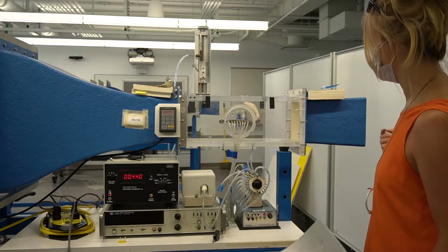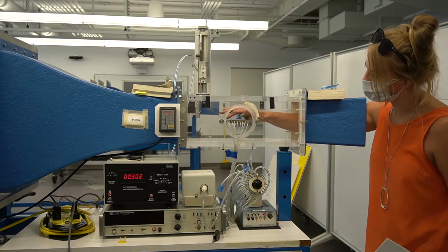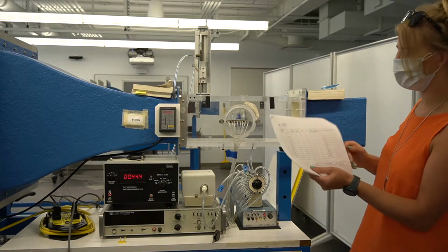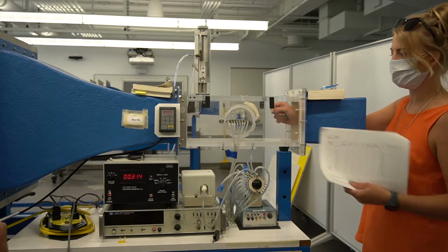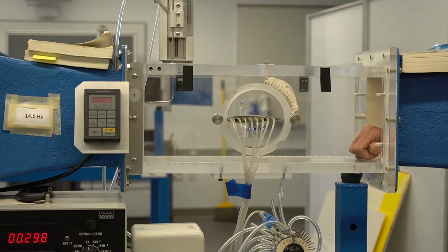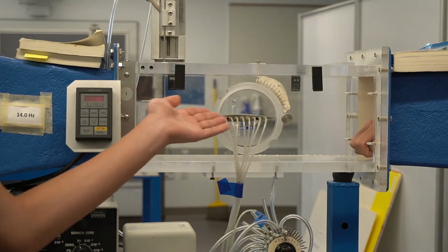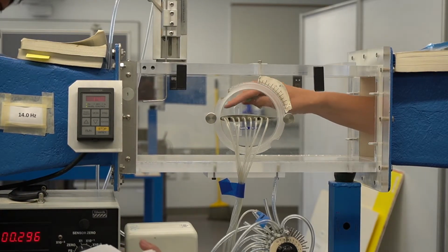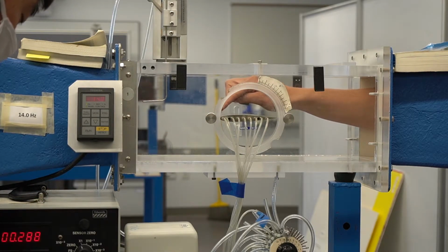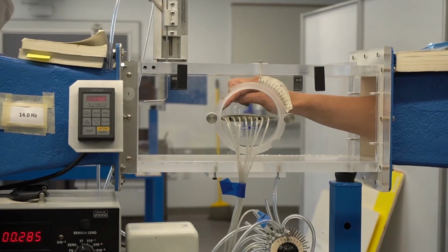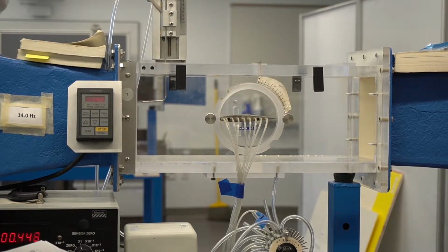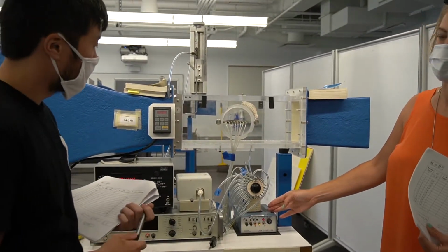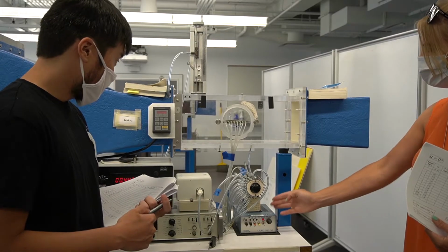So each of these correspond to a little hole on this top surface of the airfoil. And Jay, do you want to talk about what they are? X over C? Yeah, so similar to FM1, each of these pressure tap locations corresponds to a certain location on the airfoil. So we start with pressure tap location number 1, which is PT minus PS. Again, we're using the scanning valve to cycle through all our different pressure taps. So number 1 is our PT minus PS.